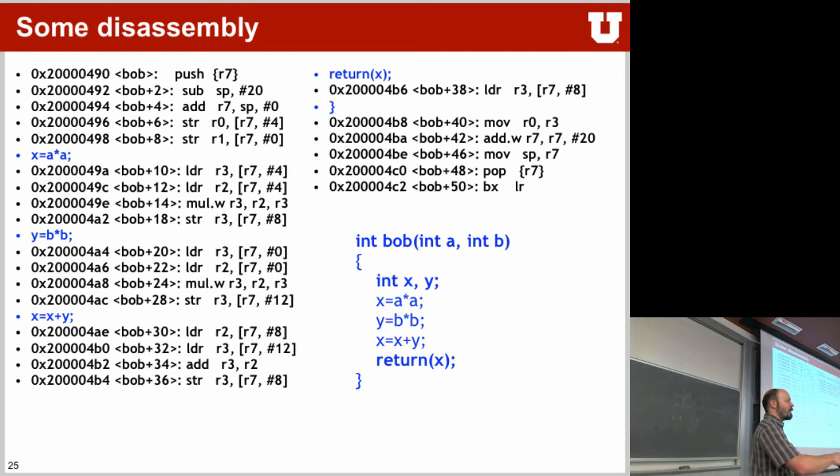We now have 5 values, registers, that we can play with. It will then store the stack pointer in R7. It will store in R0 a memory location R7 plus 4. And then in R1 it will be R7. Right? So it reads the stack out. It writes into the stack.